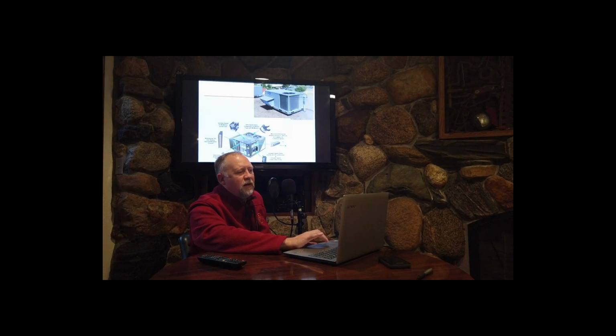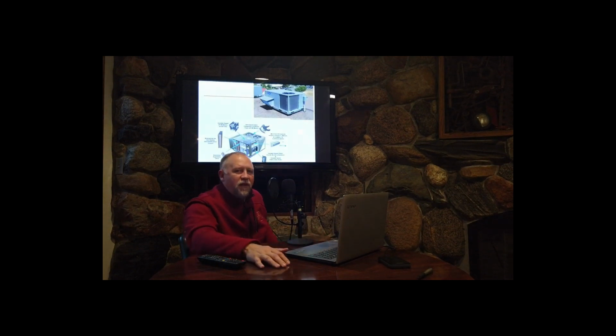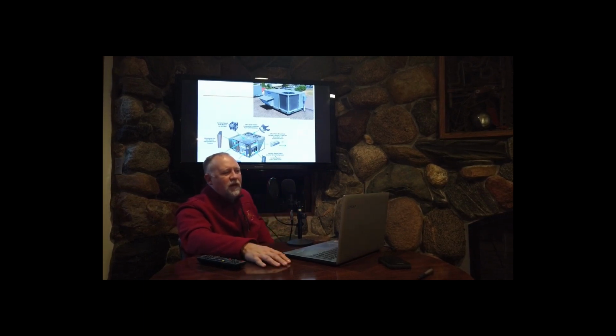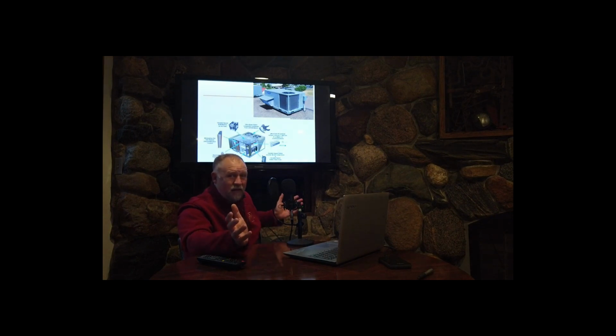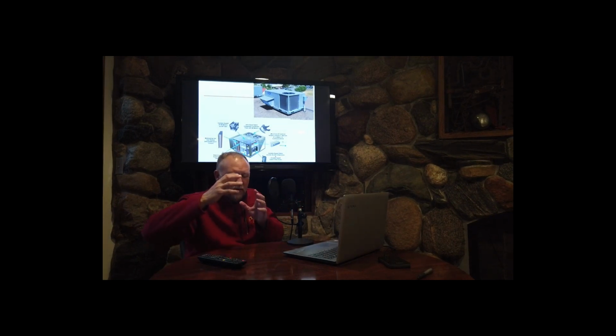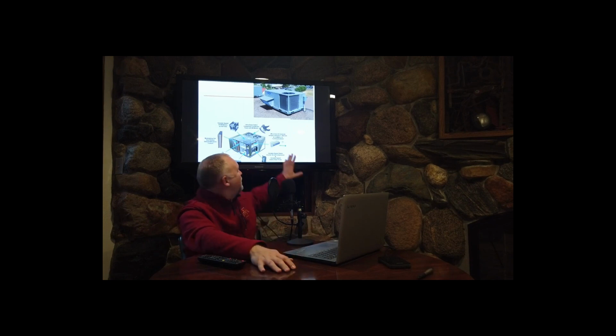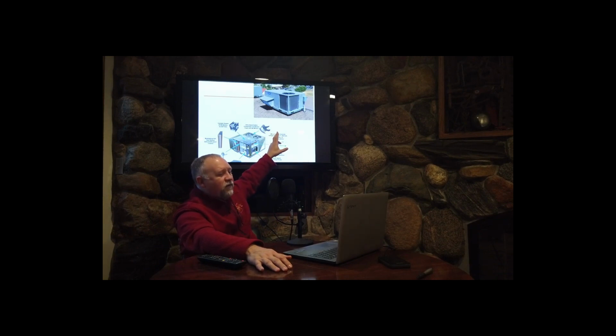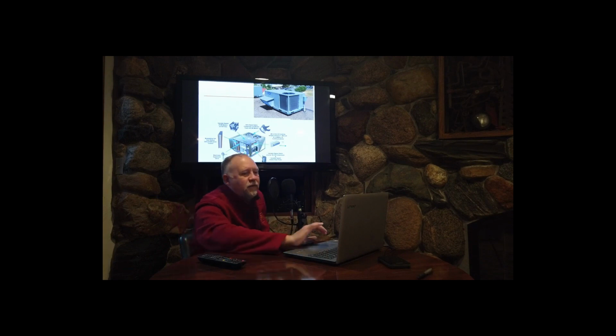A rooftop unit, here's a better illustration. Think of a simple, small commercial building with a low-sloped roof. They're going to put a rooftop unit on it. It's essentially the same thing. It's just sitting outside, and it's blowing down. That's really the only difference. It has all the same parts: filters, fan, air conditioning system. And we'll talk more about the air conditioning system for rooftop units later. But it also has natural gas going to it, and it has a burner section.